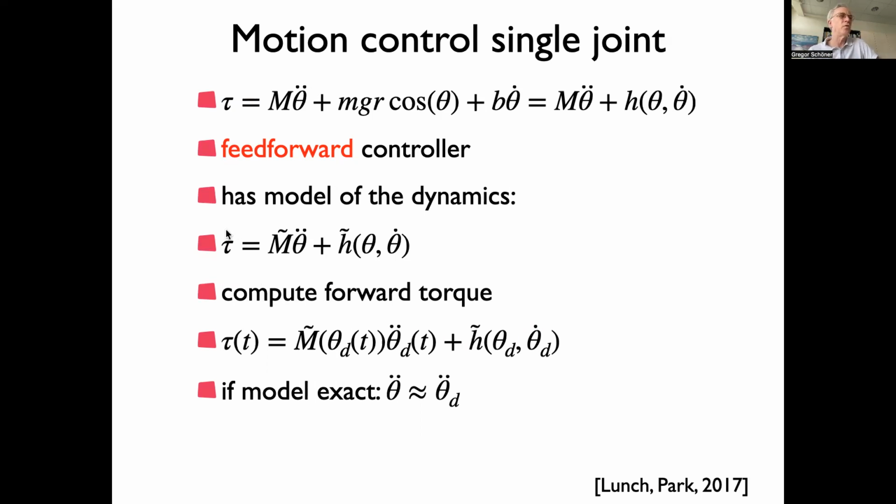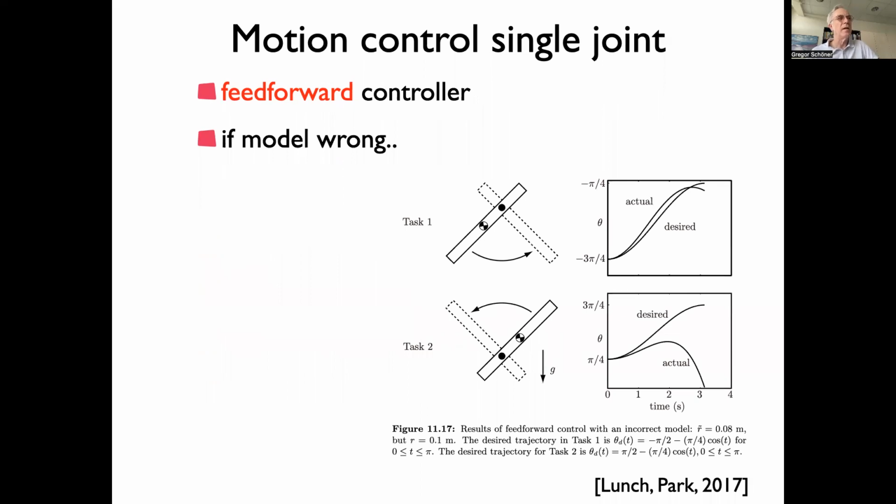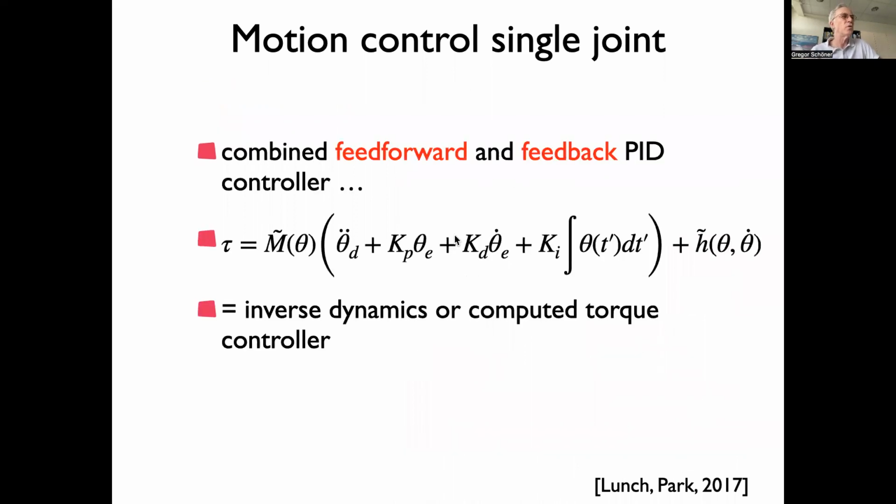So by choosing the torque to have that form, you're essentially canceling that, right? If you write that torque here on the side, then this term is supposed to cancel that term, and this term is supposed to cancel that term. And so in practice, you're combining these two things. So you see that will not in general work because there will be some discrepancy, and this is an argument that around certain positions, this can really become very dramatic. Now, it's not so bad when you have a stable situation, but in an unstable situation, you could see that that could lead to some real discrepancy where a small change in the actual physical state will lead to a real deviation. So what you do is combine these two.